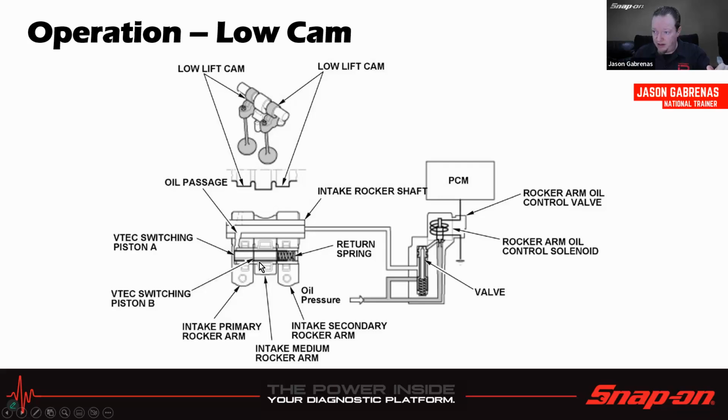And you notice how there's a break in between the pin on this side and this side. That means the rockers will follow the outer cams, right? Because those are riding directly on those outer rockers. These are the rockers here. It's just a cross section, right? So it's going to go like that. There's an oil passage in the middle.